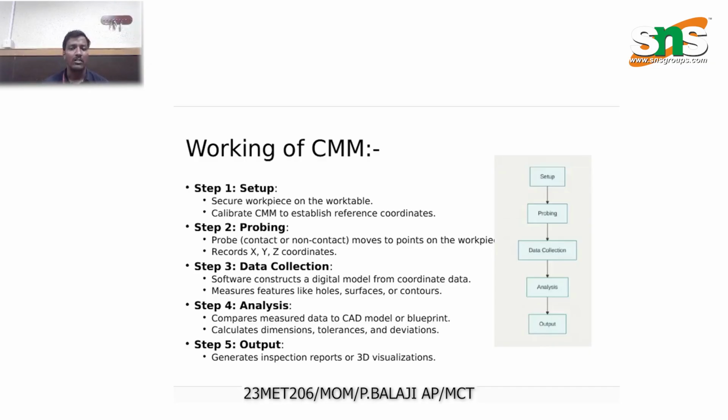It moves to the points of the workpiece, like the X, Y, Z coordinates. Then, using transducers, data collection occurs: the software constructs a digital model from the coordinate data and measures features like holes, surfaces, and contours. In analysis, compare the measured data to CAD models and the blueprint, and calculate the dimensional tolerance deviations. Then generate inspection reports and 3D visualizations. Those things we have to consider for working with probing systems.